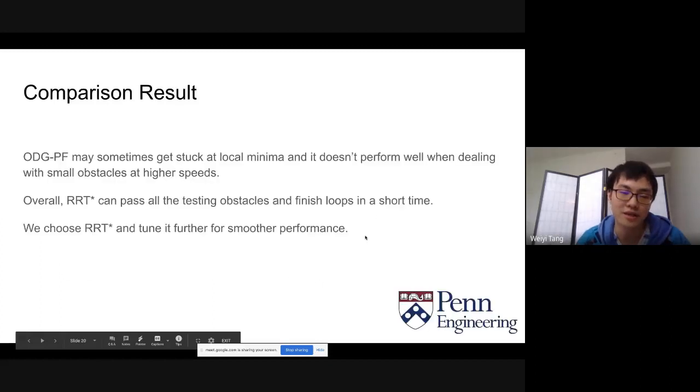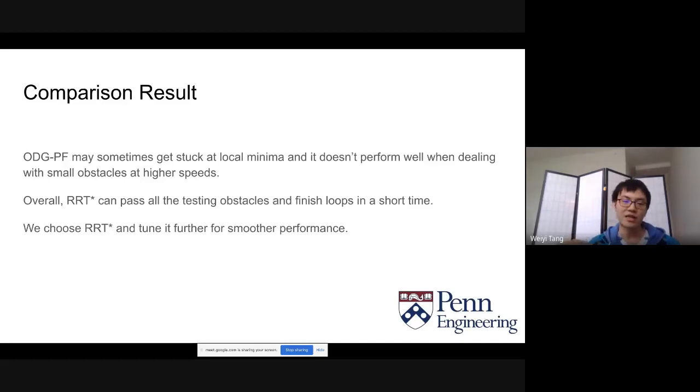So our conclusion is that the potential field method, when we implement it, is sensitive to the obstacle. If we set the distance threshold to 2 meters, then if the obstacle is 2 meters away, it will perform some behavior to try to avoid it. It also vibrates a lot because it's not very stable. We wrote some stabilizing algorithm on that, and it still vibrates a lot.